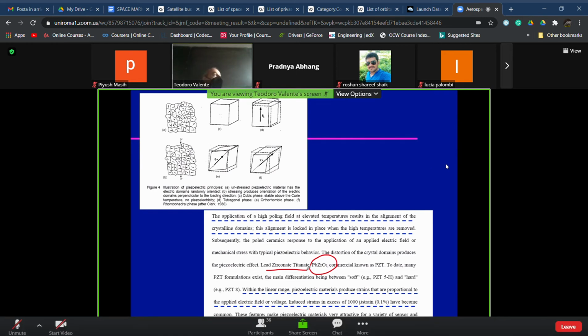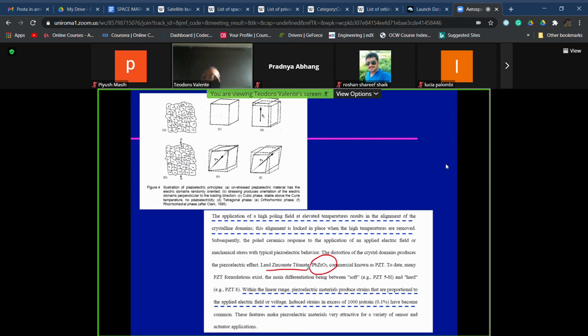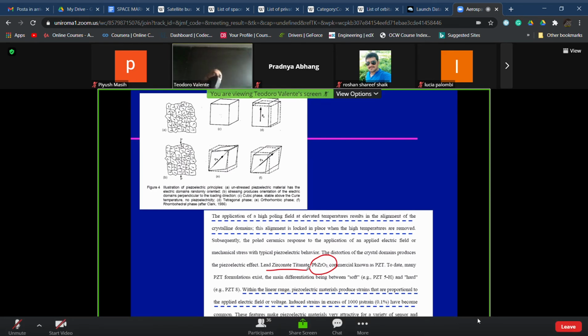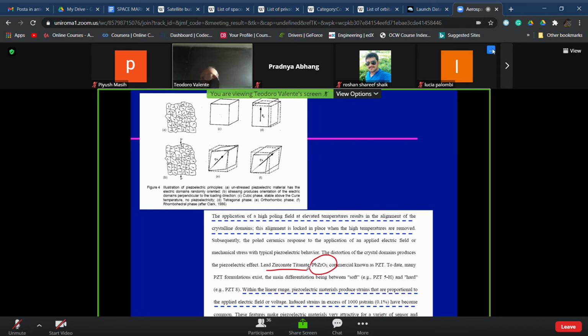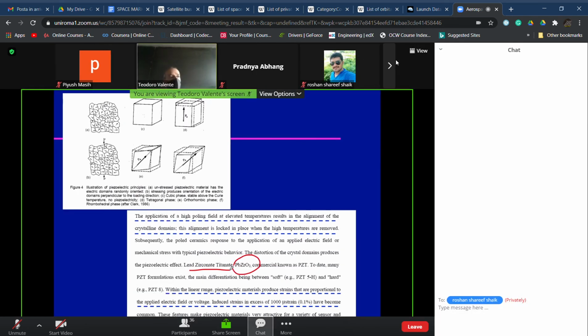So if we have some polymers which can show a piezo effect, one thing that could come to mind, not the only one, but one, is to place this polymer as part of the matrix of a polymeric composite-based material, in order to have, for example, a sort of health monitoring of the component itself, because that polymer material, when stressed, if it has a piezo behavior, can give back a voltage.